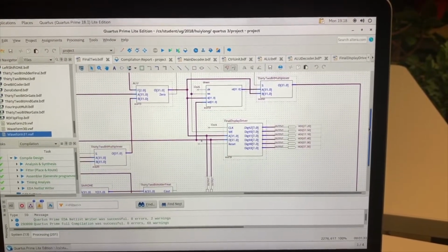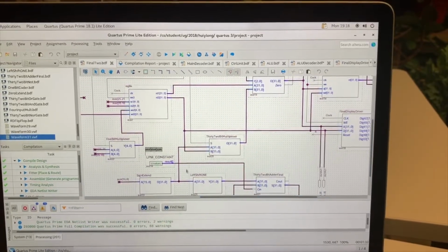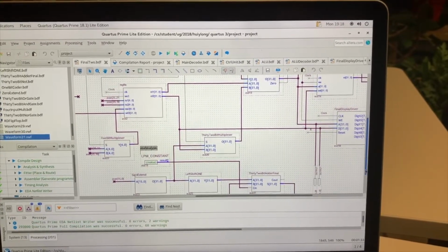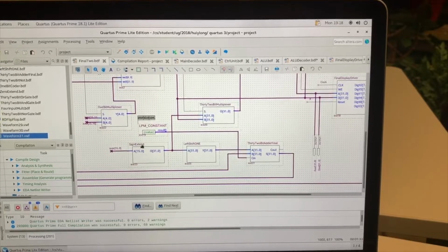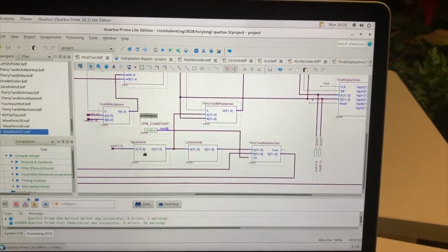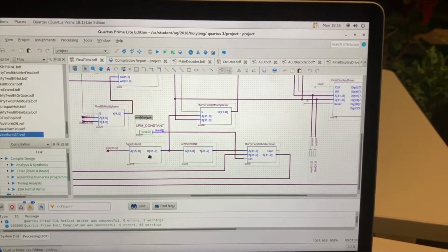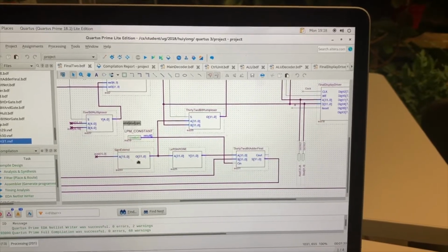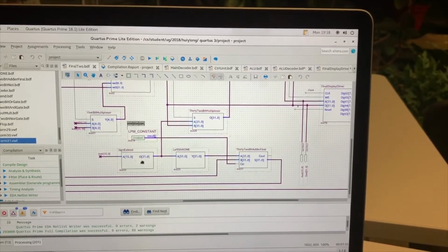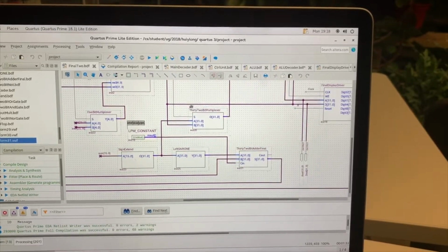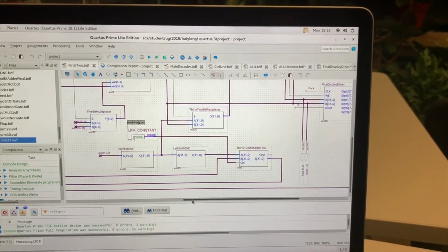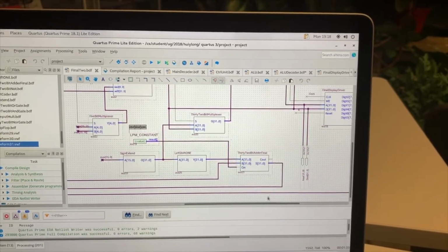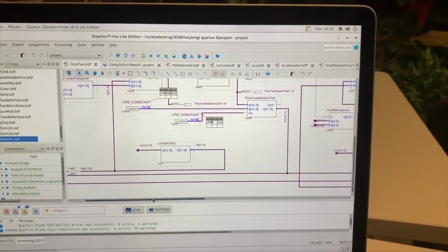Moving back to the sign extend. The sign extend extends the number to more bits. The inputs are 16-bit. However, the immediates are used in the 32-bit register. Sign extend is used to convert the 16-bit value to a 32-bit value by filling the first half. For positive immediates, the first half is zeros, while for negative immediates, the first half is ones. Then, the output is delivered to the left shift and the 32-bit multiplexer. From the left shift, the value is multiplied by 4 and it feeds into the 32-bit adder, which then outputs to the 32-bit multiplexer here.